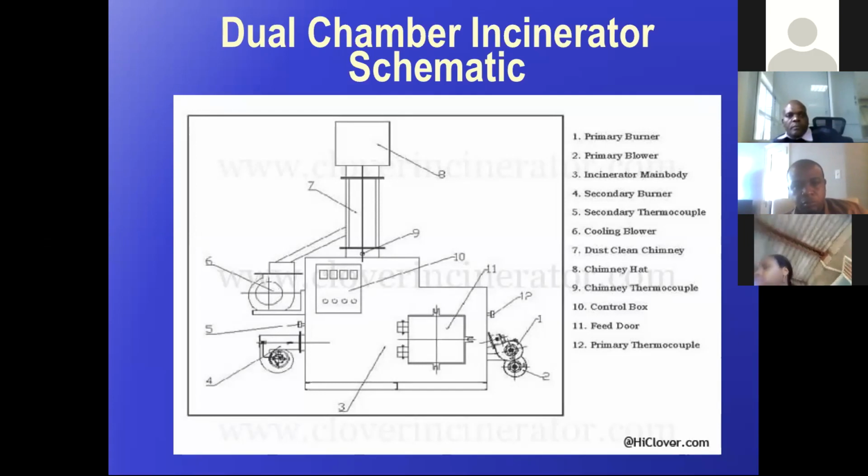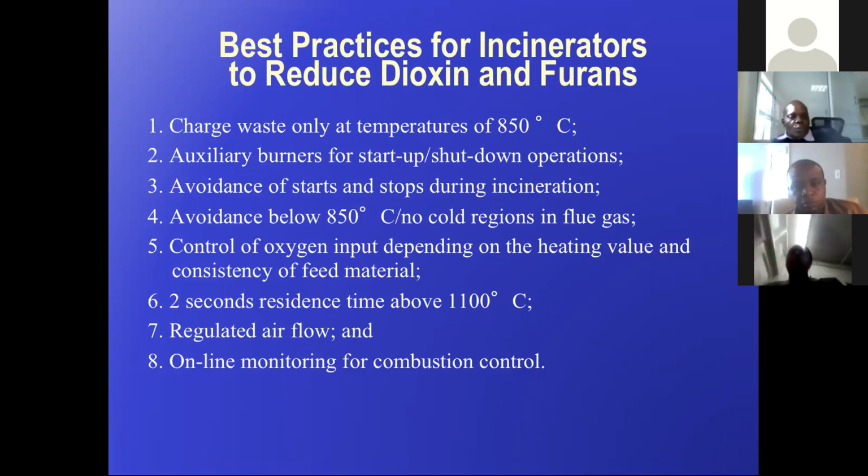So it all comes down to this, and these are the best practices that have been identified for complete combustion. What it comes down to is making sure that you have the proper temperatures. Even when we look back at the different designs of incinerators, if we don't have a dual chamber incinerator, and there might be some single chamber variations at your facility, it's important to have those high temperatures. That's really the crux of the message here: to ensure the temperatures are at a high enough level to ensure complete destruction. To have high enough temperatures in the primary chamber, and if you only have a primary chamber incinerator, it's still to get the temperatures up there.